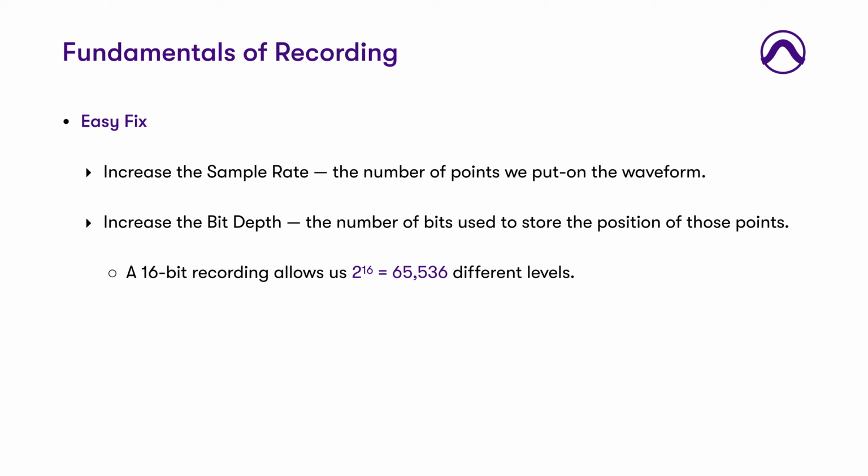Now imagine using a 24-bit system to record. A 24-bit system gives us 2 raised to 24, which is nearly 17 million unique values that we can assign to our samples. This means we can achieve an even more accurate recording using 24-bit bit depth.